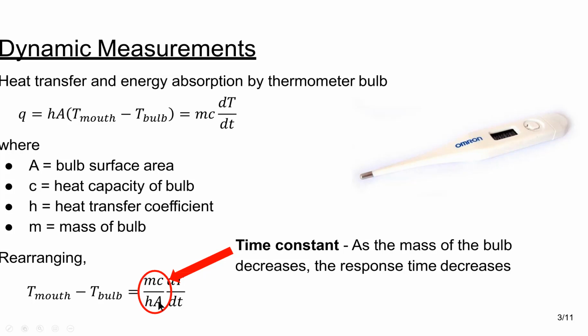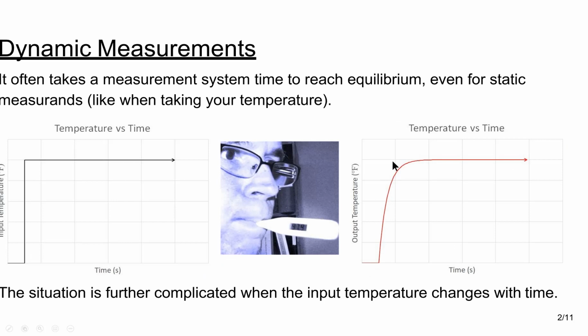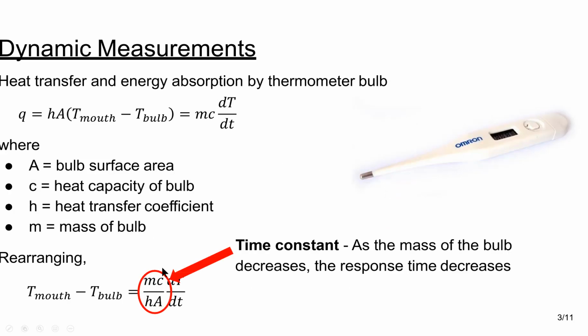And so these are more or less a constant, with the potential that some of them change tiny amounts, but they're tiny enough that it doesn't actually affect anything that we're trying to measure on the scale we're trying to measure them. So these four get lumped into what's called a time constant. And so that time constant kind of controls this part of the response of your system. So it controls how long it takes for your measurement system to get from its initial state to its equilibrium with the thing it's measuring state. And so that time constant is, in this case, built of these four items.